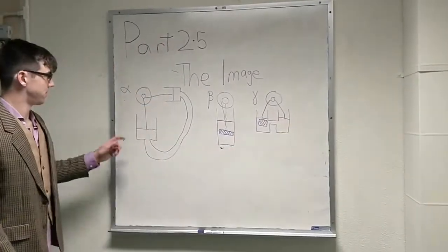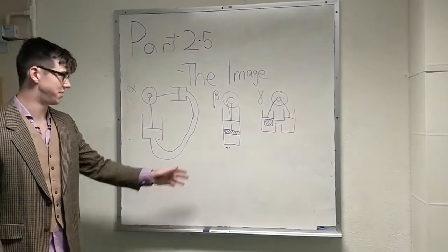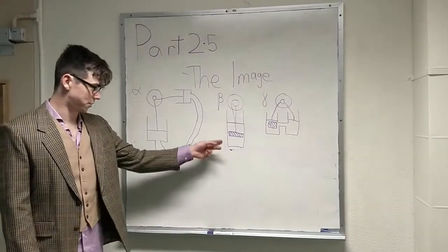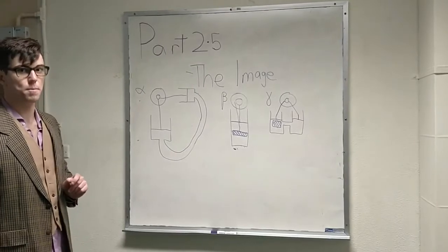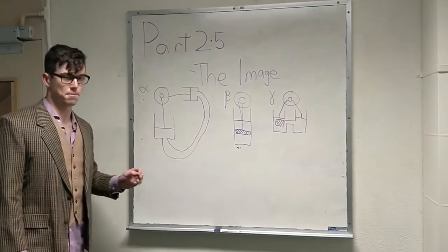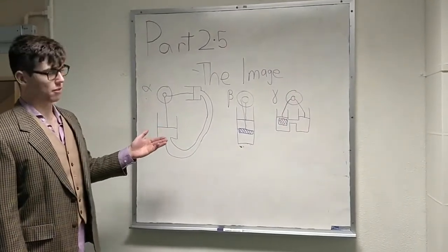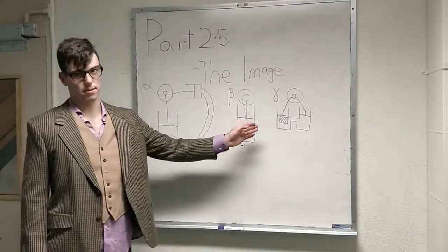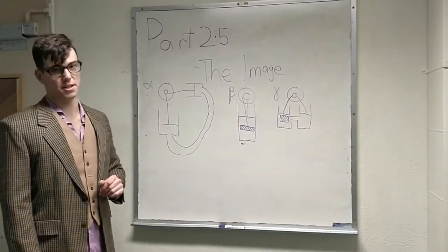In general, the alpha and the gamma engines tend to be more efficient than the beta type engine because of the close proximity of the hot and cold chambers in the beta engine. I've decided to build an alpha engine as it's more efficient than a beta, and it's much simpler to build than a gamma engine, as getting the displacement in there is quite difficult.